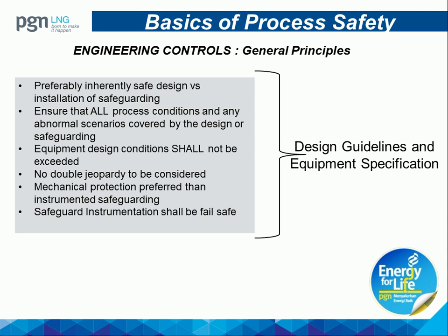The next one is mechanical protection is preferred over instrumented safeguarding. Why? It's because the integrity level of the mechanical protection is normally higher than instrumented safeguarding. And then the last one, but not least, is safeguard. If we implement, or if we install safeguard instrumentation, it needs to be fail safe in any case. And normally all these general principles you can find in design guidelines or the equipment specification or any standard provided in your own company.